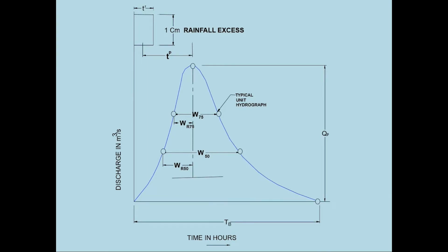Tomorrow we will take an example of how to solve that and how we will arrive at it. So this is a unit hydrograph, which I have already explained. The y coordinate gives the discharge in meter cube per second, and the x coordinate is the time in hours.